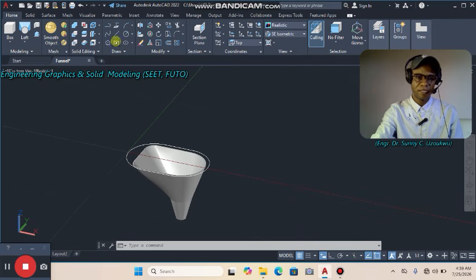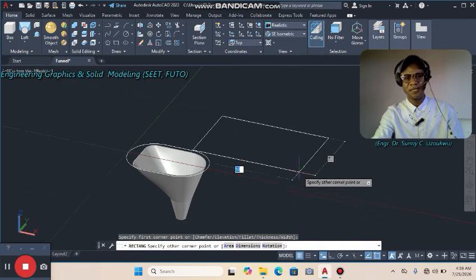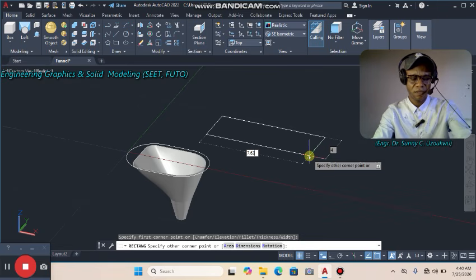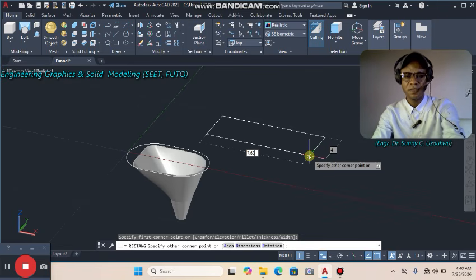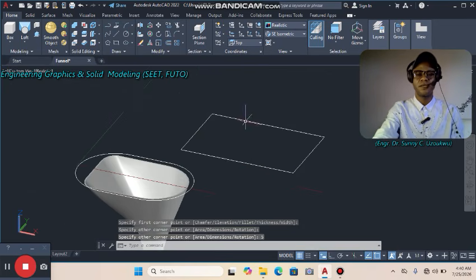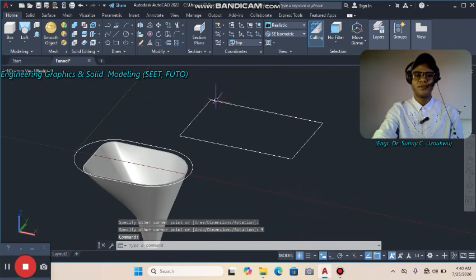Then pick up a rectangle, right? Specify the dimension, say 6.625 against 5 or 5 point something, depending on what the choice is, for teaching's sake. Then we've got it. Then to give it these curved edges, you come to fillet.